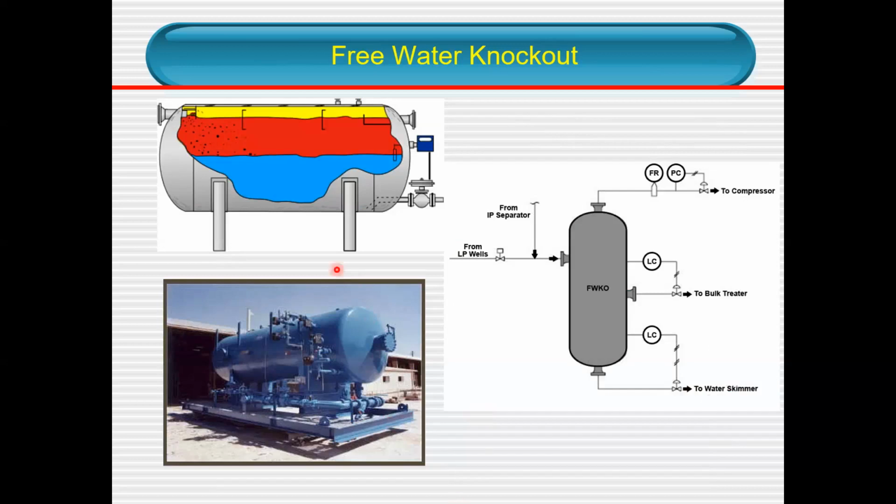As you can see here, these are typical separator mechanisms. It just has elements for chemical injection. This is vertical and this is horizontal, with chemical injection so that you can get clean water, below 40 parts per million, and free of other contaminants if there are any.